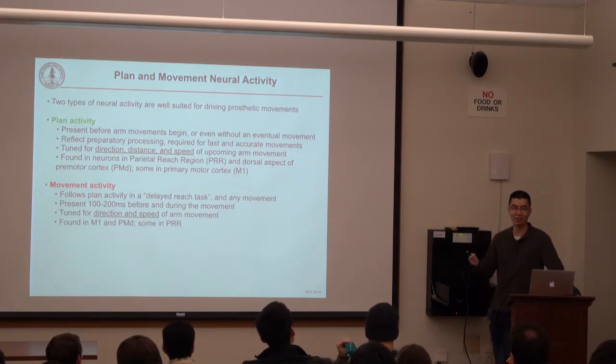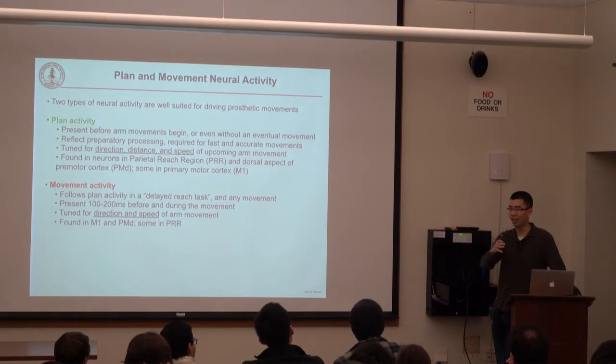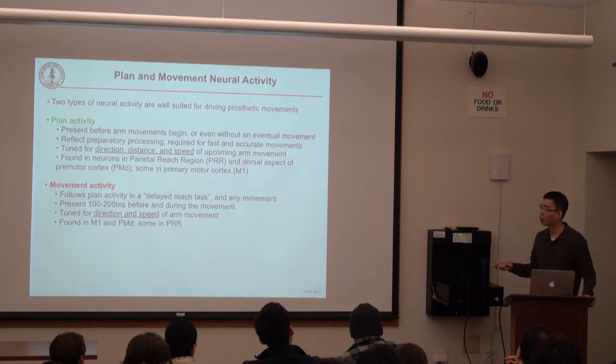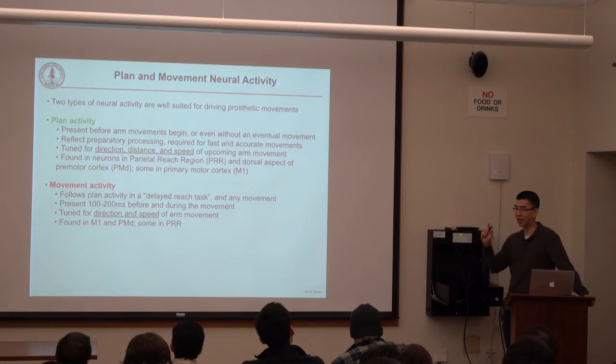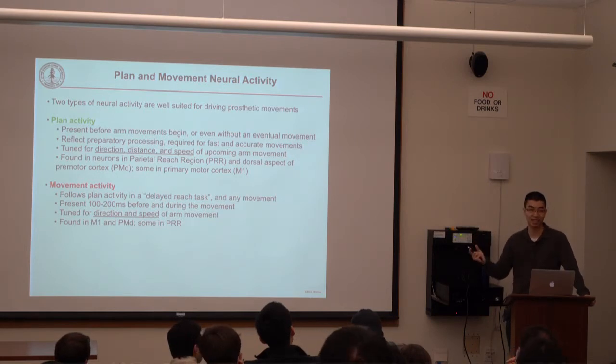Let's imagine that I made a command, but the decoder took a second to process all the neural signals and then respond. That would be a horrible decoder to use, because it's going this way, and you want to say, oh no, I want to go this way. But you have to wait a second for that command to actually start to affect the decoder. So you have this long loop time, and that could be really frustrating to use. You're correct that all the processing that we do is slower than this latency. And really what we want to do is make that latency as small as possible, on the order of maybe even less than 10 milliseconds. And that's actually what we have in the lab these days.